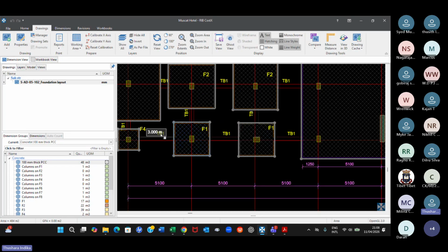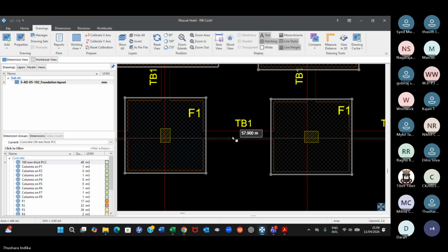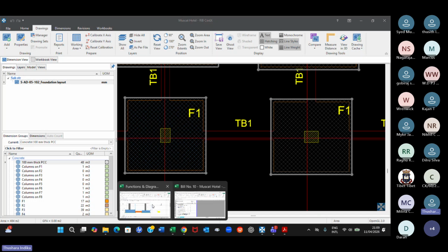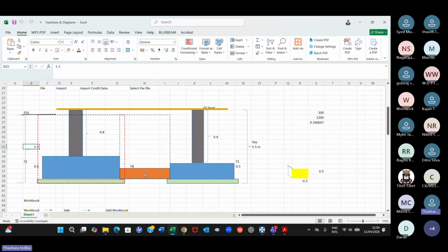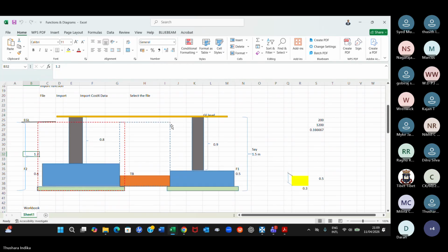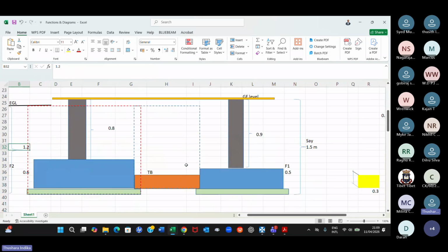You can see here, there are tie beams and then there will be trench excavation. Again, if I go to this diagram, you can see trench excavation. This orange color section is the trench. This is an elevation or maybe a section. And this is your beam. And the beam is sitting like this between two footings. And then you have to excavate a trench, which is reflected in the blue dotted line. You can see here, this line, that is your excavation for the tie beam.